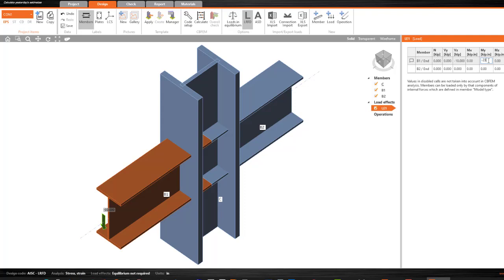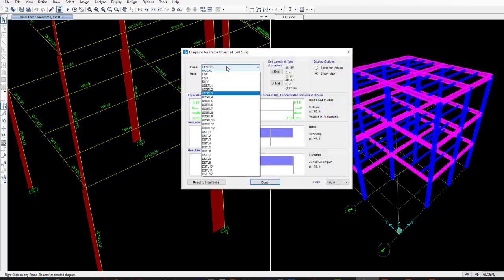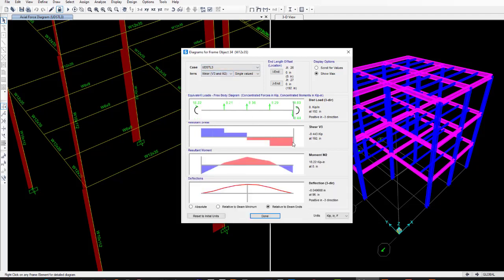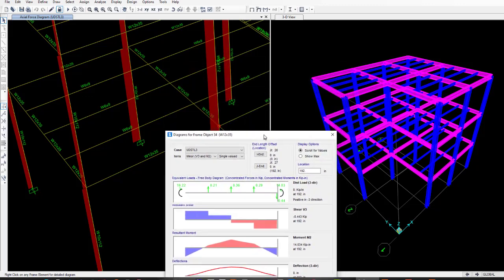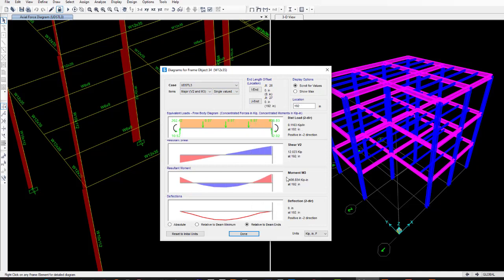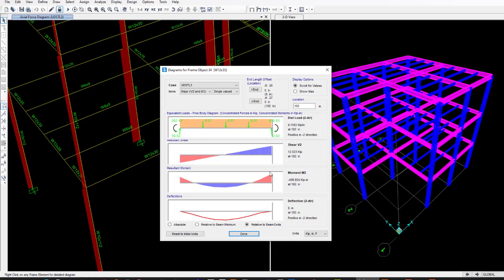This is foot by inch. We have to check, use foot inch, and then go here, check this beam, the shear force. This is moment, shear, and shear should use V2, not V1. Yeah, because here we're using about 12 kips. 12 kips, we use 10, and this is 12 kips, and the moment should use moment 3 here.